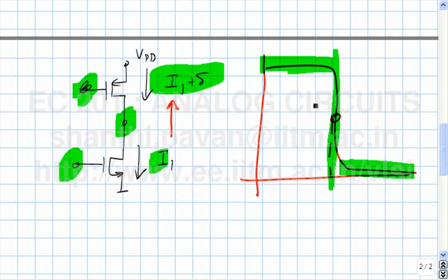If you have a nonlinear characteristic of this nature, where the incremental gain is very high in a small region, then you must be very, very careful in fixing your quiescent operating point. Alright? And then, one of you may ask, so what is the big deal?